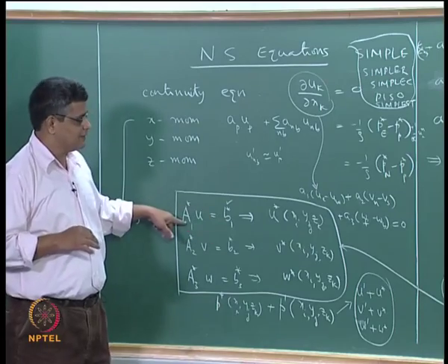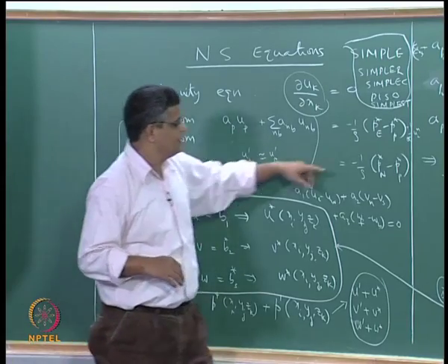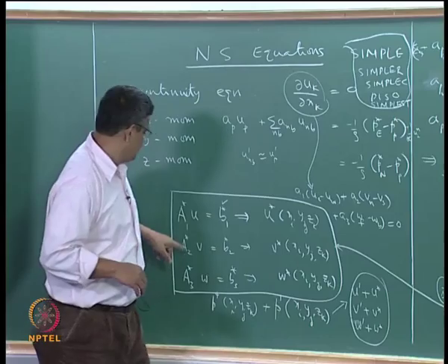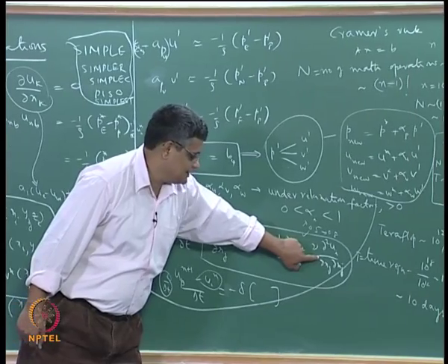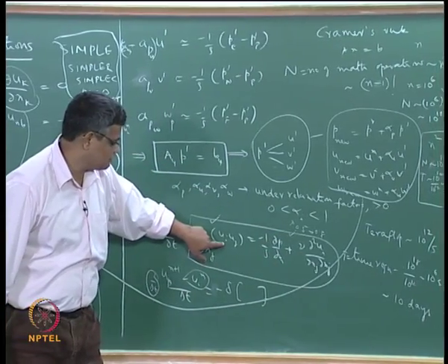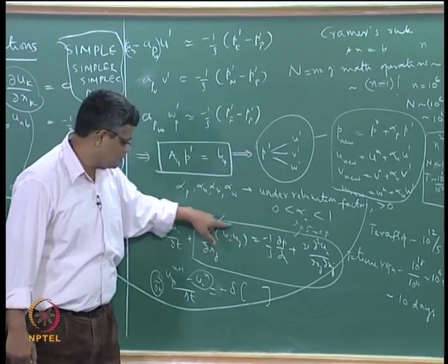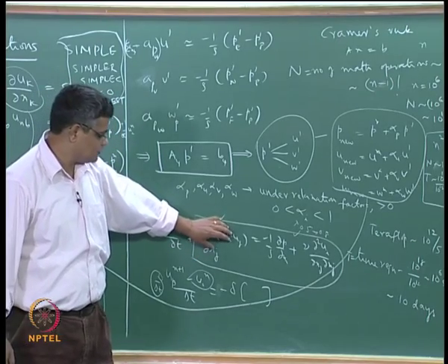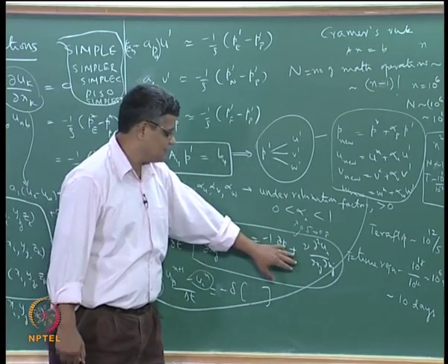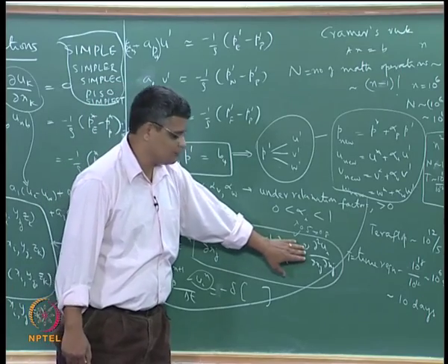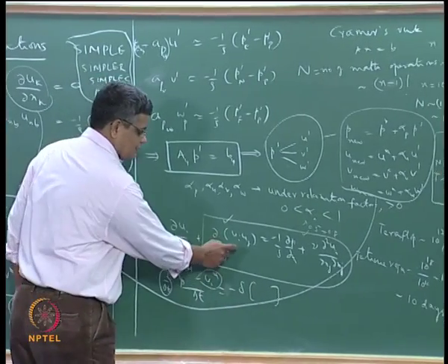We see the origin of these things. In the simple case, b1 comes from the pressure gradient and maybe from the previous time step value, and a1 comes from the diffusion equation and also from the advection term. In the simple laminar flow case, this constitutes a nonlinear term, whereas this constitutes a linear coefficient. So in a simple laminar flow case with constant properties, this will only give us linear, constant coefficients, whereas this can give rise to